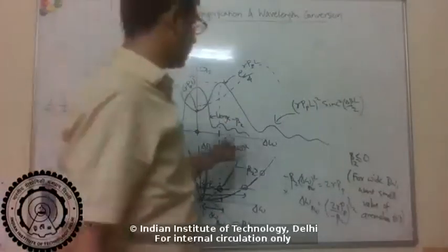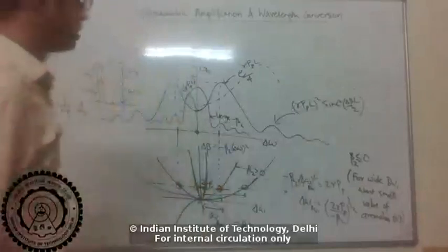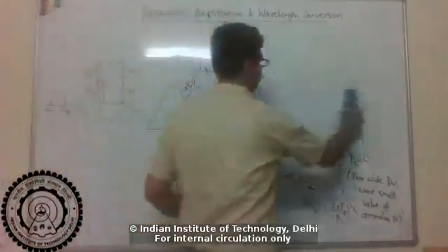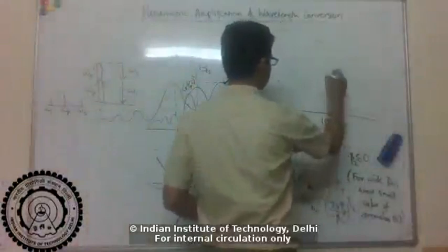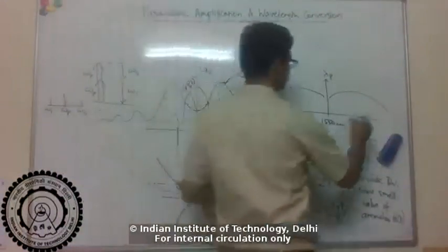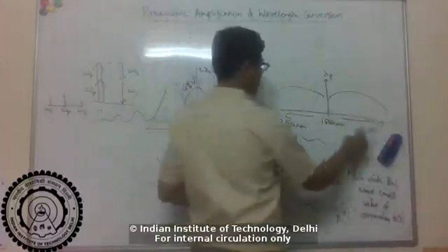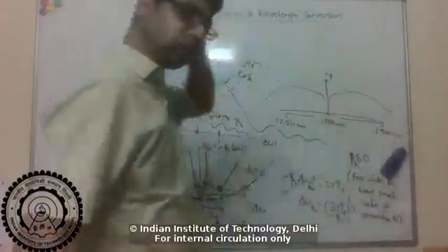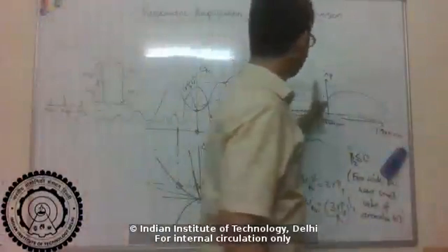Okay, so the ideal case you want is negative beta 2, but just slightly negative, right? Not too much. That will give you a very wide bandwidth. So typically, people have demonstrated bandwidths of hundreds of nanometers. Let's say the pump is at 1550 nanometers. People have shown these four-wave mixing based amplifiers for hundreds of nanometers on either side, so this is going from, I don't know, like 1250 up to like 1900 or something. Using fibers and silicon waveguides, etc., you can adjust the parameters such that you can get very wide bandwidth.